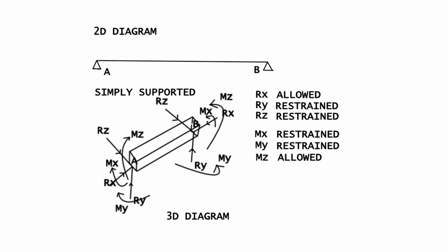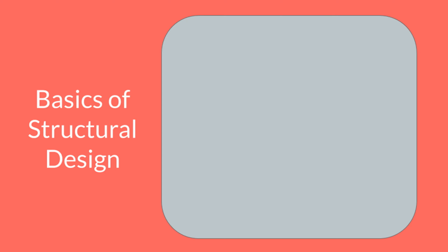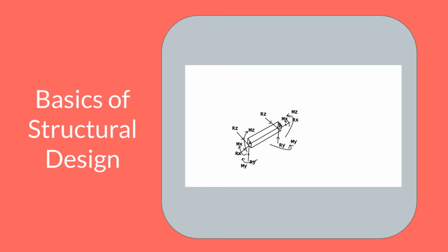Joints. It is important to understand the types of joints and their provision at a selected joint. That is like column to beam, beam to beam, and slab to beam, etc. At each support, there are 6 degrees of freedom, 3 for translational displacement and 3 for rotational displacement. To understand the concept of degrees of freedom, let us consider a bar with a flag. To hold it in position, all the 3 translational displacements and 3 rotational displacements shall be 0.